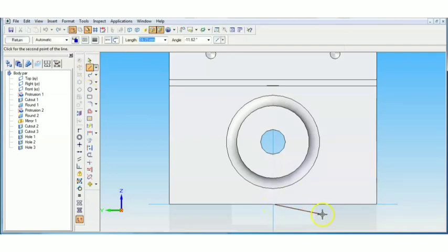From this center, 30 mm, and 0. This side it has to be 10 mm, and inside it has to come by 4 mm, and again further of 3 mm. Come to this point, just extend beyond it. Just you can type from here as 30, angle is 90, connect it here.